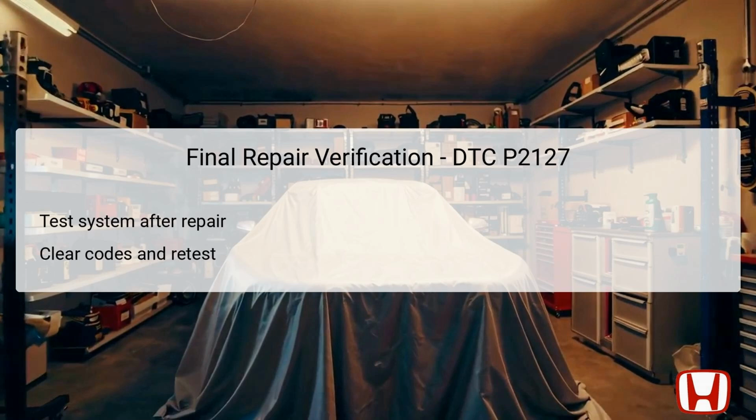Following this, the ignition should be turned to the on position to power up the system. The HDS needs to be employed again to clear any stored codes, including the P2127 code. After clearing the codes, the technician should perform a road test or simulate conditions to ensure that the system is functioning as expected without triggering the trouble code again.